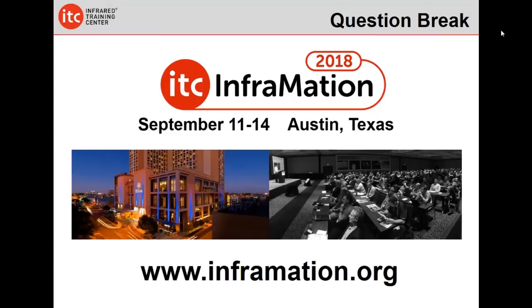Let's see. Another question. We'll take this one here. Best way to span and level with the FLIR XT radiometric series camera. What are people's options for adjusting span and level? Well, in your controller, you're going to have several options, and those options allow you to eliminate background, increase background. The best option, as far as I'm concerned, for still images, for static images, is to get the best focus we can get and do thermal tuning in FLIR Tools. And we're going to talk about FLIR Tools later in this presentation as well.